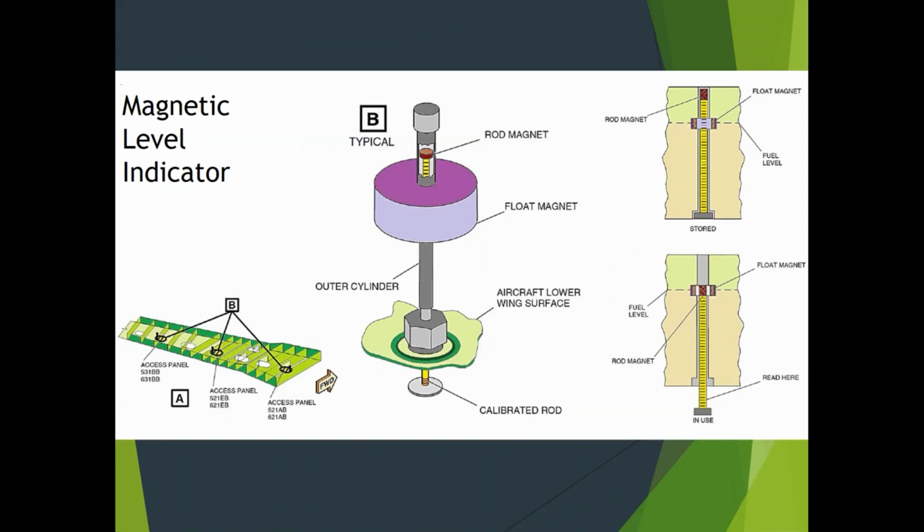You know how a metronome works? You've got this long fiberglass rod with a big weight on the end. It would sit there and rock back and forth all the time, and that would cause them to break off. So that's why you want that float to always be sitting supported by the fuel, rather than being held on the very tip of the rod all the time.